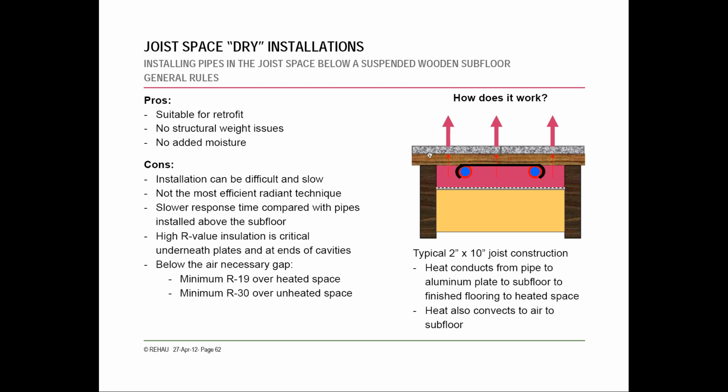Now, that being said, if you're using a standard building technique with a house and you want to add radiant to a smaller zone, it doesn't necessarily make sense to change your whole design to accommodate the small radiant area, maybe in, say, a couple bathrooms upstairs in addition to the standard slab in the basement. So you may end up specifying this type of design or wanting to install this type of design, and that's fine. But just make sure you're taking all of these steps we'll touch base on into account to make sure you can drive as much of that heat upwards.